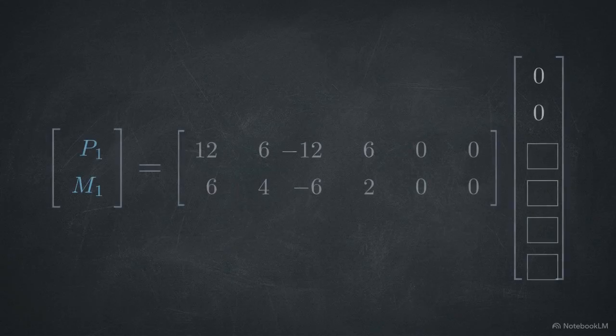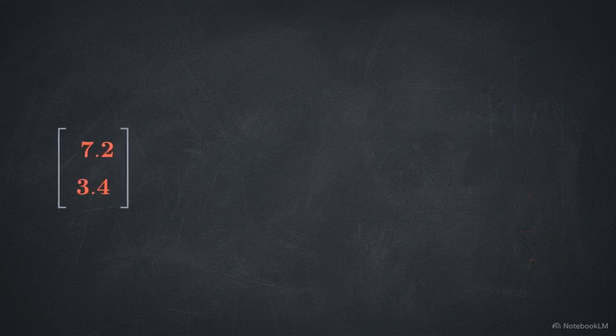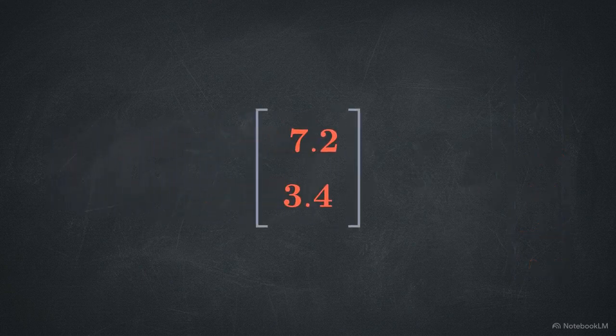Recall the rows sliced away during the matrix partition phase. The displacement vector in this secondary equation still contains empty variable slots. We take the calculated numerical answers from our primary deflection solve and feed them directly into this discarded equation. Because all displacements in the vector are now known numerical values, standard matrix multiplication can be executed across the row. This final multiplication yields the exact physical reaction forces occurring at the boundary conditions.